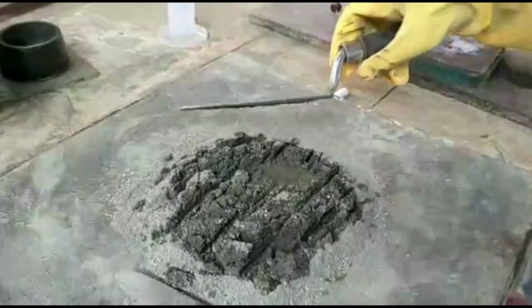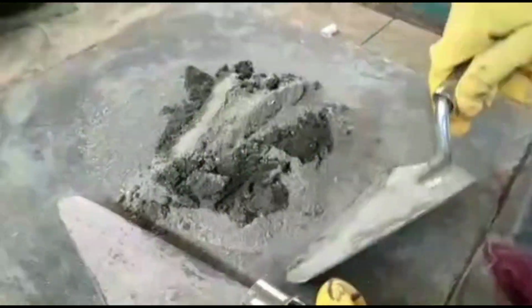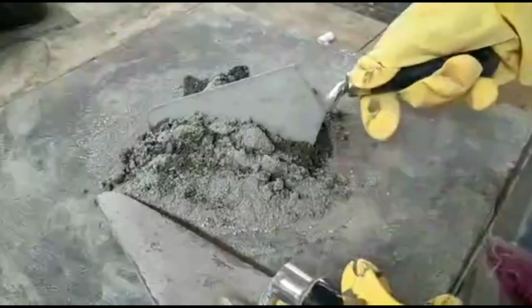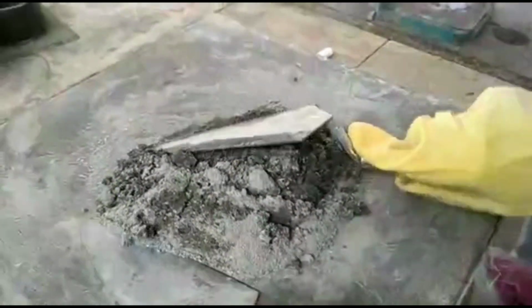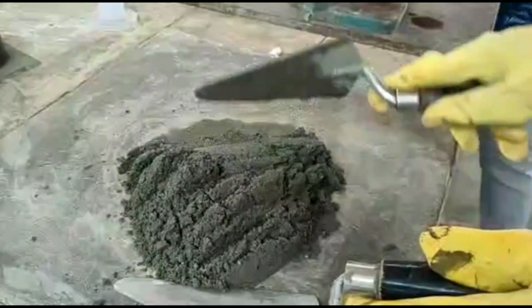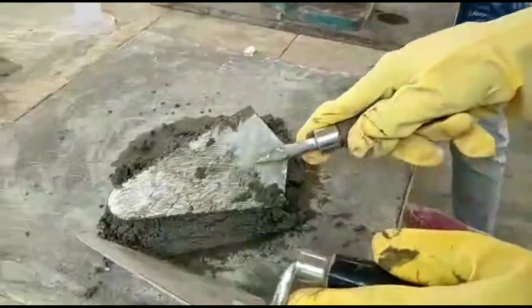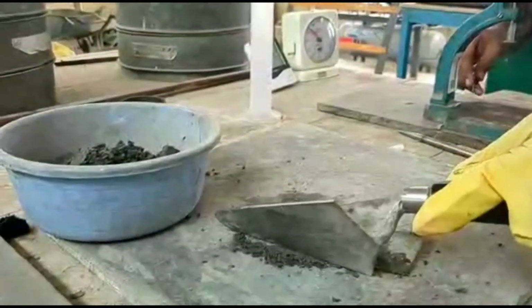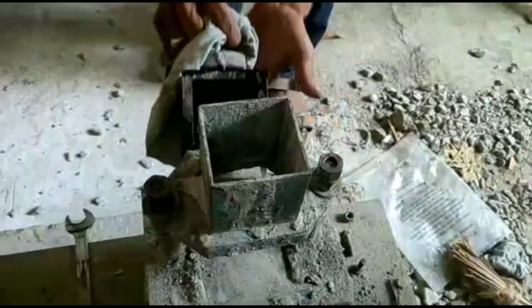Usually the compressive strength of hardened cement is the most important of all its properties. Therefore, it is not surprising that cement is always tested for its strength in the laboratory before it is used in important works. Strength tests are not made on neat cement paste because of difficulties of excessive shrinkage and subsequent cracking of neat cement. Here we are preparing test specimens according to IS 4031 Part 6, 1988, methods of physical tests for cement: determination of compressive strength of hydraulic cement other than masonry cement.